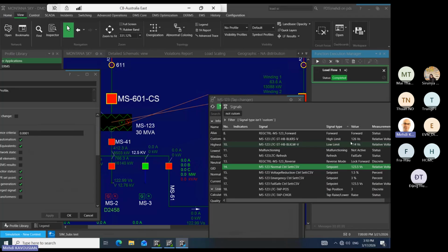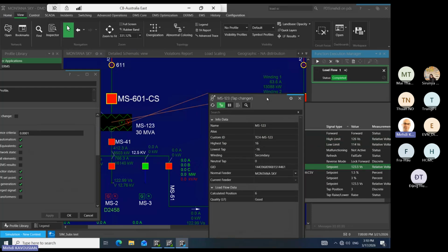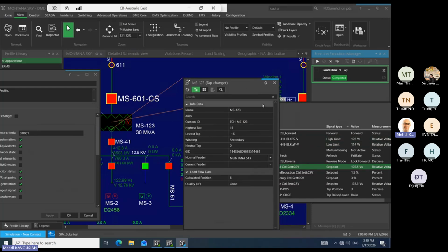If you put 7 steps, it goes higher. You never get exactly to that. So that's the combination of that bandwidth and this set point, which determines how that set point is calculated. Why do we have this mechanism? This is especially important when we do simulation, because in simulation you assume that if your load changed, the tap position reacts to that and keeps it in the limit. If we don't have this, the load flow is not realistic, right? This is more for voltage.